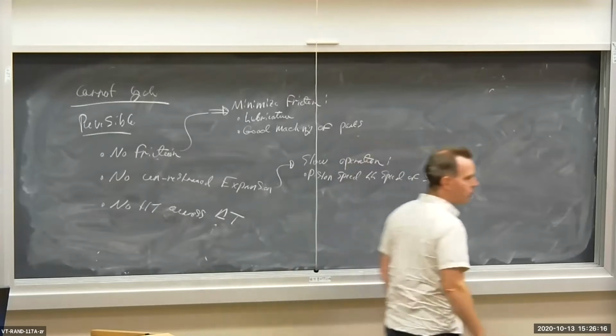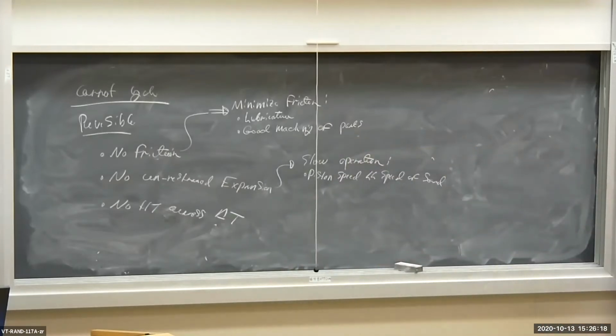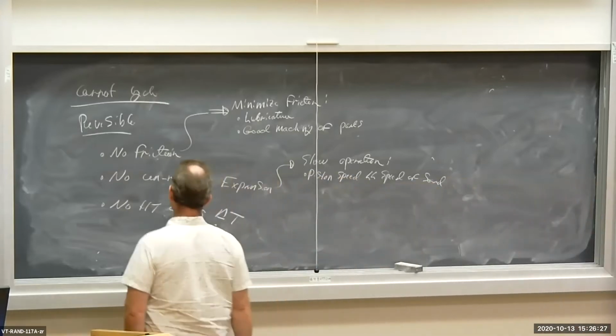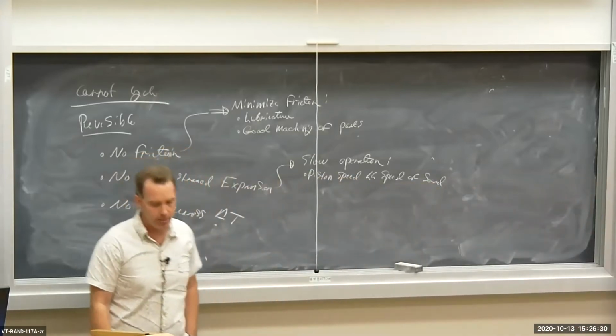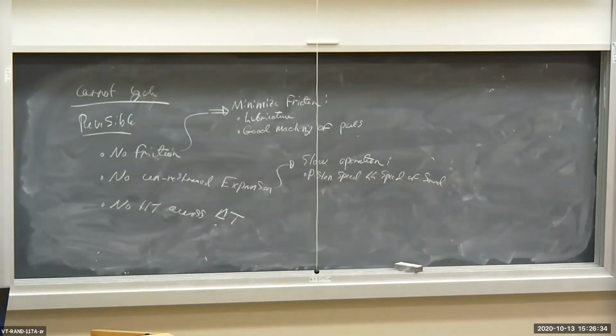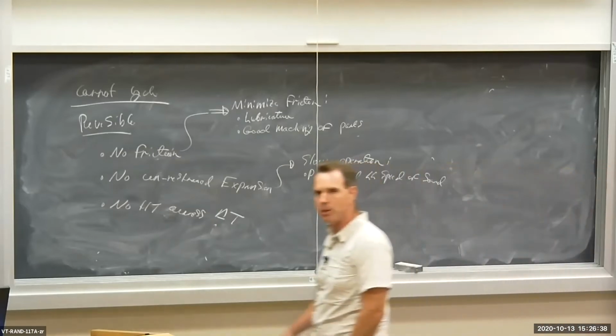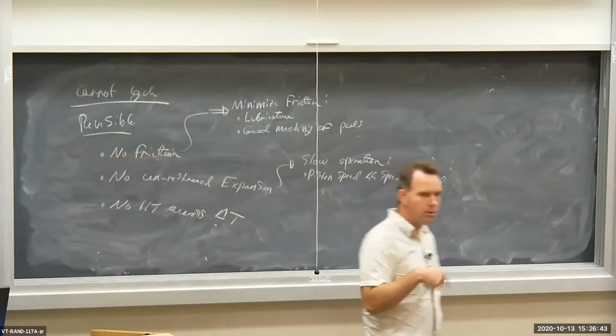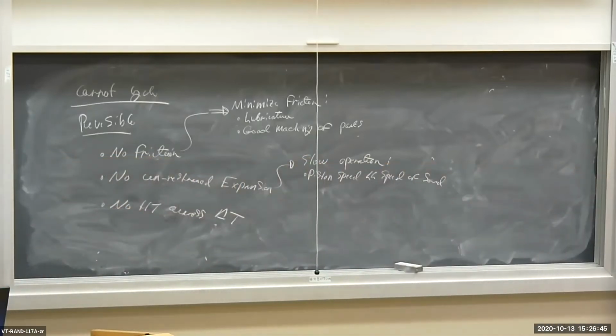Speed of sound is the speed at which a pressure wave propagates through a gas. And pressure is how a gas responds. A gas responds due to the movement of a surface due to a pressure wave. So if the pressure wave can't keep up with the piston, you're going to get some kind of unrestrained expansion. So piston speed, much, much less than the speed of sound. So that's a way we could have slow turning piston cylinder devices or engines, and that would minimize the presence of